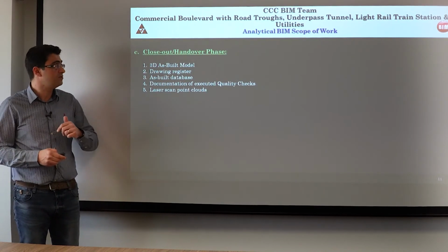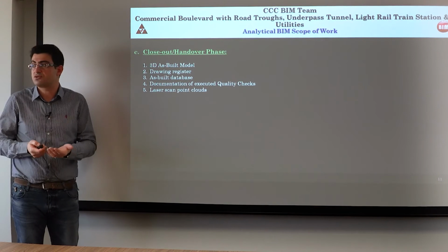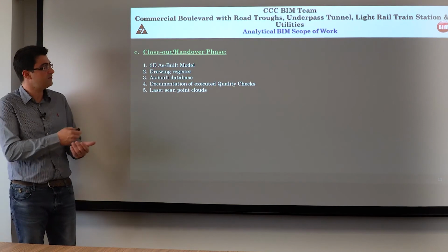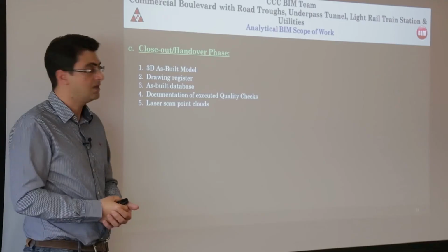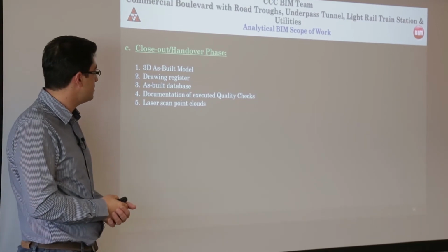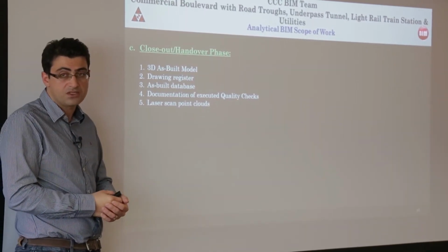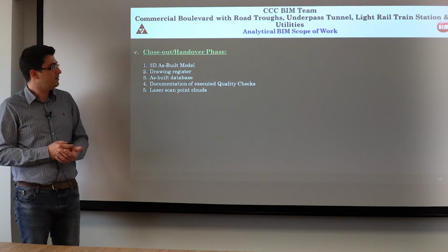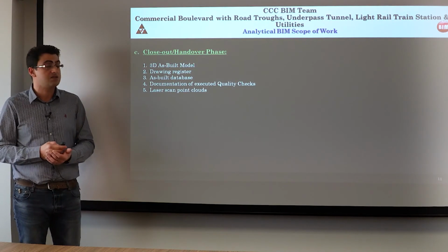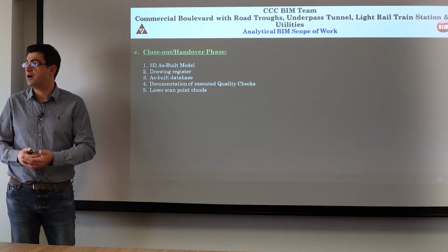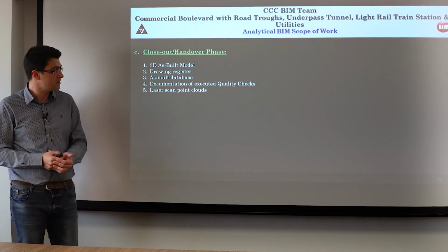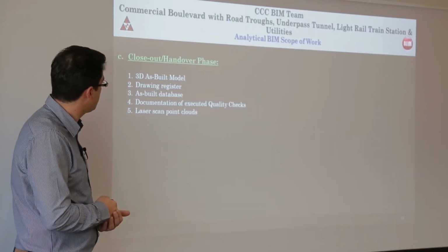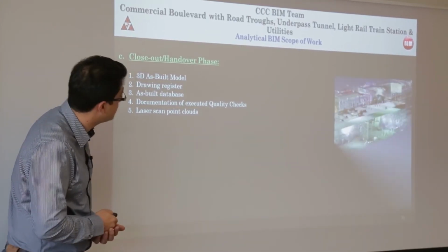Additionally to that, we had to utilize another phase, because it's not just the early phase and the implementation phase, it's the closeout phase. In the closeout phase, we have the final 3D as-built models, the drawing register and model register, the as-built database, which will consist of all the quantification data of the as-built model, and the documentation of the executed quality checks in order to verify that those models are correct as per the as-built drawings, and of course, the laser point scan point clouds, as you can see here.